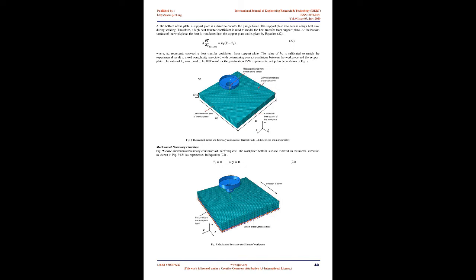Results obtained in the work of Ashby et al. 38 suggested that steel sliding on aluminum results in a friction coefficient of 0.25 in a dry sliding test at ambient temperature. Sundar Arjun et al. 23 found that the friction coefficient varies between 0.4 and 0.5 according to the welding condition. A constant friction coefficient of 0.3 was used by Schmidt and Hattel 19. Numerous elements such as temperature, contact geometry, and applied force affect the friction coefficient. Zhang et al. 6 conducted a detailed study on the factors affecting the friction coefficient for the FSW process.